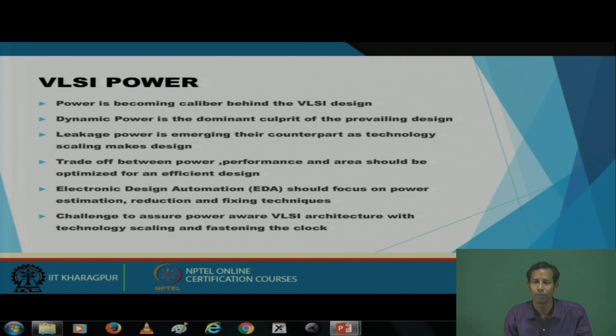But if the tool does the static timing analysis, then it takes each of these paths, computes the timing analysis for each, and then shows you a report. From there, if any of your timing constraints is violated, it will immediately report that this particular path is violating it.